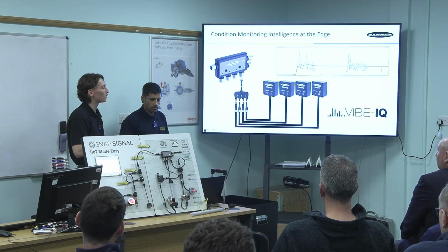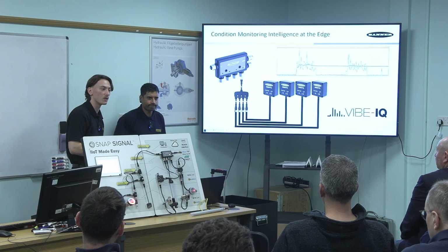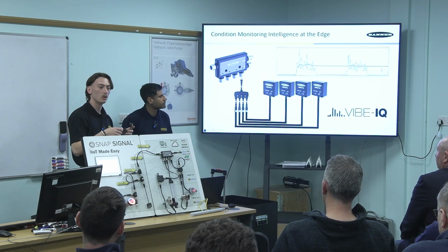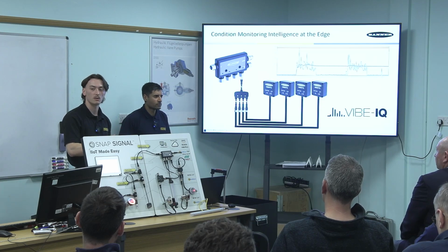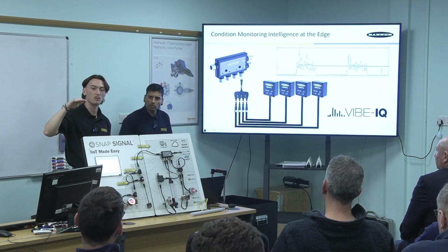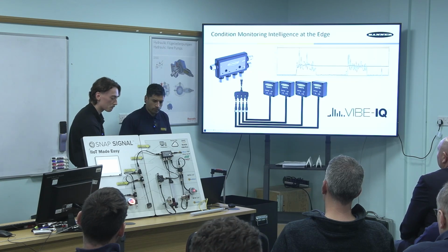So once all your sensors are mounted, you trigger that action to start the learning process, and over 24 hours it will collect enough data for it to make its own calculations on its threshold settings, so you know that this is good, this is maybe a cautionary, it's 15% above, and then again on top of that where you really need to take some action.